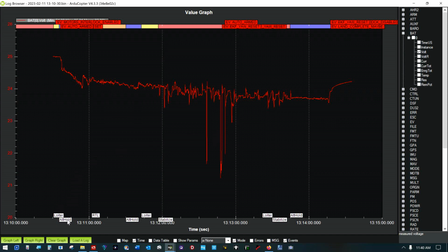You can see I ran the platform out there just like I said. Tested return to launch on it. Wanted to see how it would react to that with the big battery. Really, really heavy that way. Got some altitude hold, loiter, stabilized for a long time for this portion of it. Then back into loiter for a while. Stabilized, altitude hold, and out. Now, this battery never came close to battery failsafe because it flew last at 23.69 volts or so.